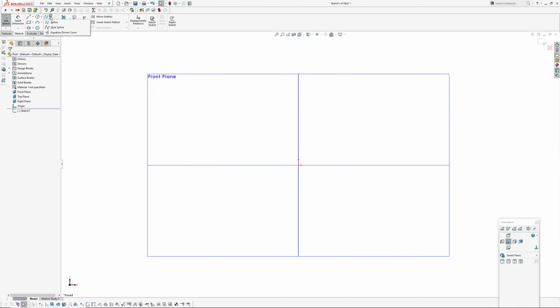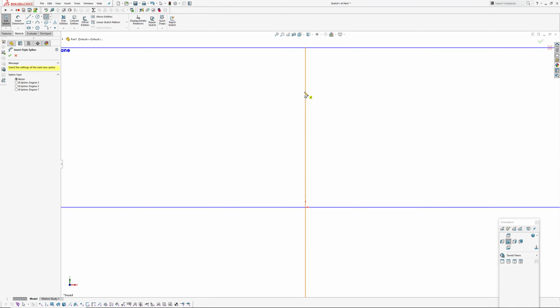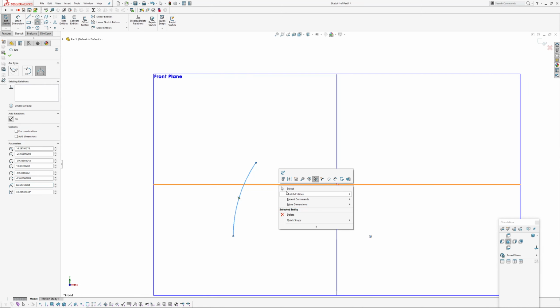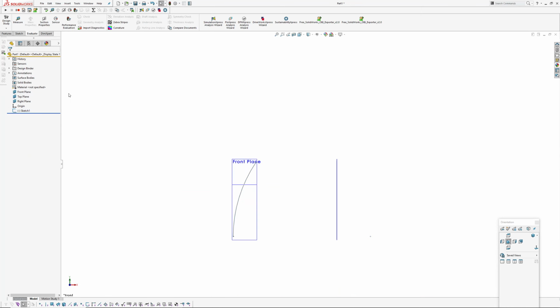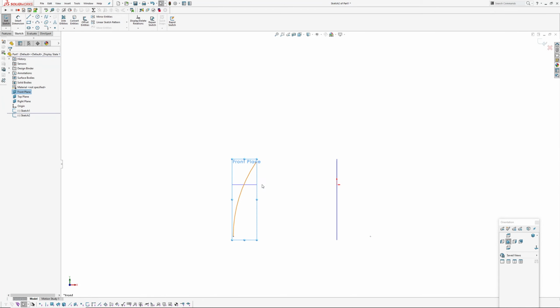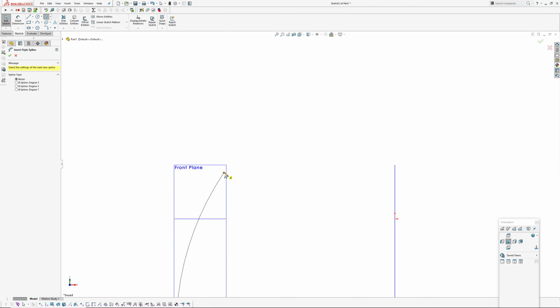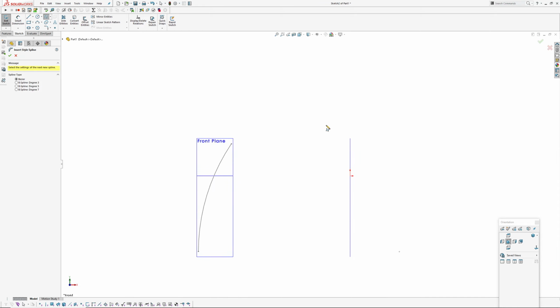You're modeling a half and you're coming off the center line. So let's pretend we've got a curve down here that could be a surface or a curve where we want to come off that curvature continuous, and then the center line we want to make it normal to the center line because we're going to mirror.